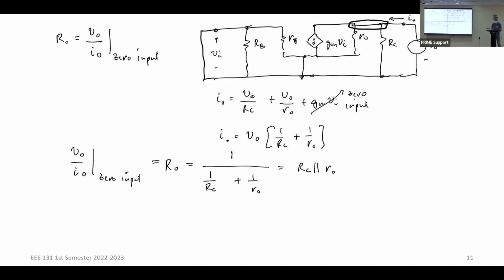Okay. Now, would it have made a difference? Would it have made a difference if my input were assumed to be a current source? I just want you to think about that. What if my input were assumed to be a current source? Would it have made a difference? It won't, no? Because if my input were a current source, ibig sabihin, I'll leave this open. No? But if I leave this open, there is no current that will flow through either of these resistors. So if there's no current flowing, my V sub I will still be equal to 0. And therefore, this will still cancel. Okay, this will still cancel.